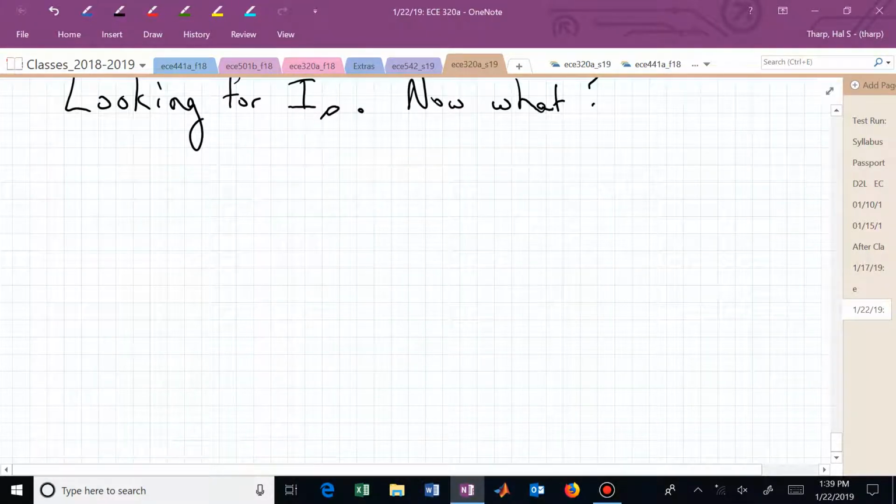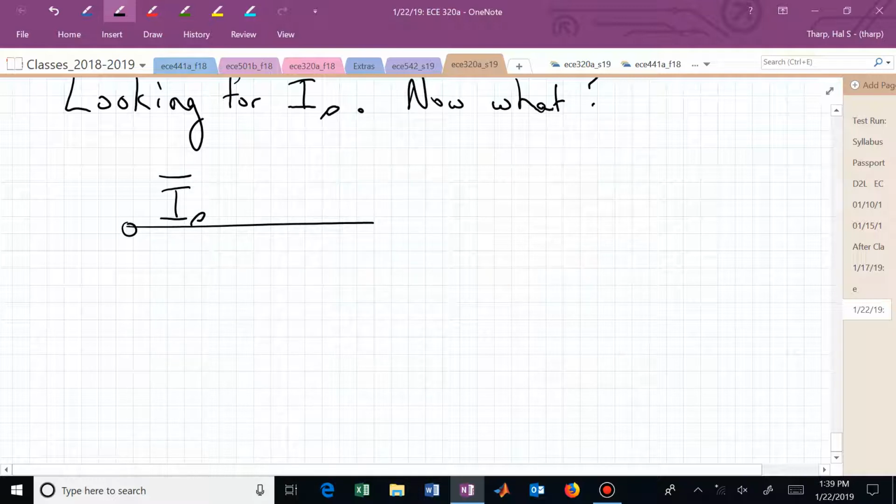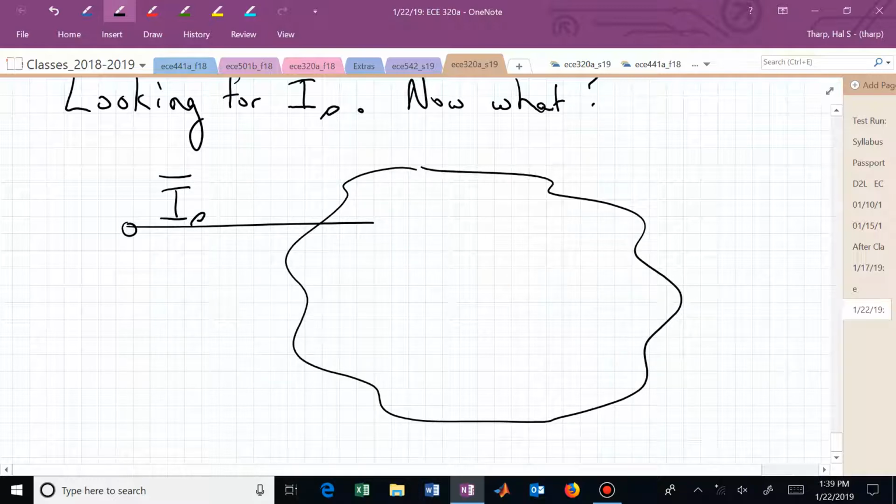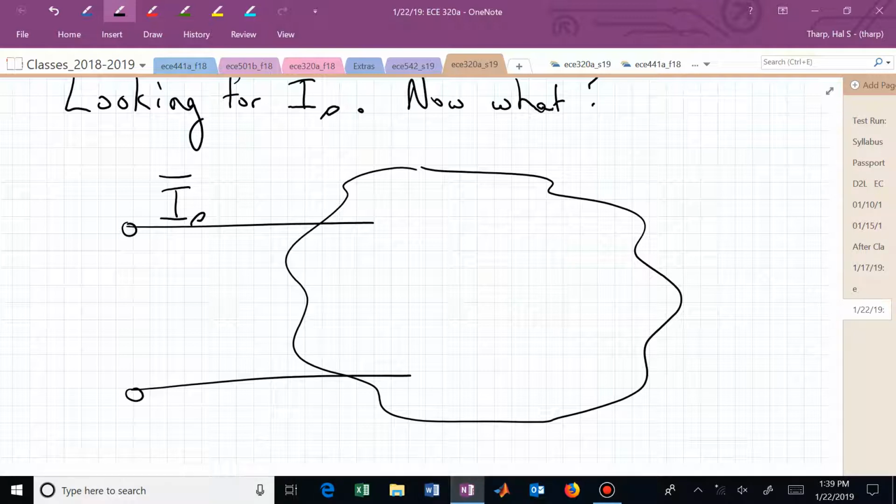Well, really what we've done is we now have reduced all of those loads down into something that really is one effective complex consumption. We now have that the total complex power of those three interconnected loads is 600 minus j800